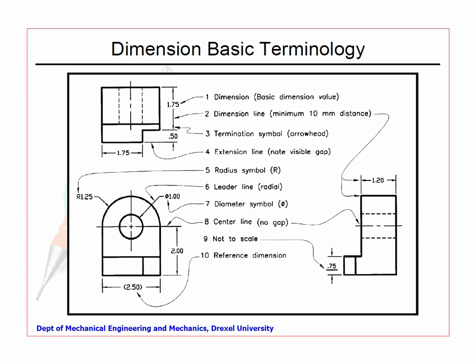The idea of a reference dimension is that no further machining needs to be carried out to maintain the dimension. Probably it is brought from the stock material, and if you maintain this R 1.25 all around and you make these things asymptotic, by definition this will become 2.5, and one should not constrain this as well as this unless it is very, very critical.